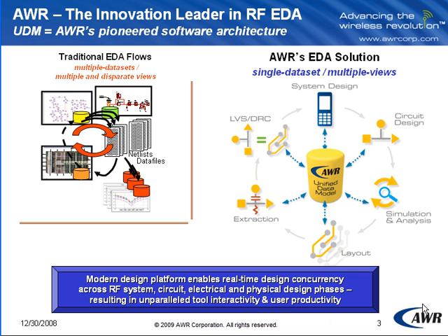The AWR design environment gets around this because, unlike other EDA tools which have a different database for every view of the design, schematic, layout, analysis, and so forth, and a different database for every technology in the design, including you may have multiple databases for different ICs, it makes it really difficult to integrate these things. In the AWR design environment, we have one unified data model, which is not only able to capture in that single data model the schematic, the layout, the simulation, the extraction, for a technology, but it's also able to do this for all the technologies. They can all be simultaneously loaded.